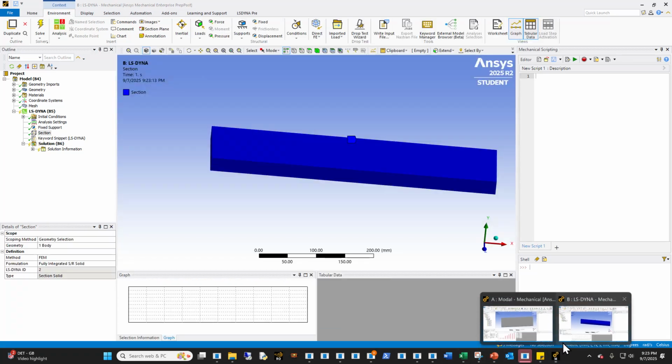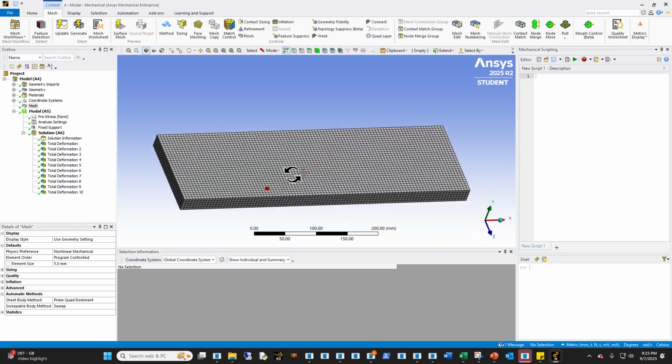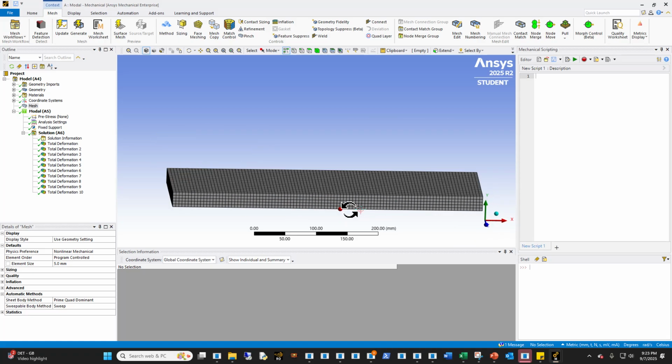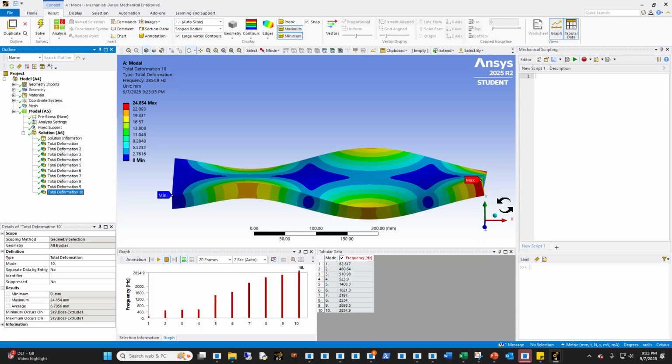In Mechanical, I think you actually default to a quadratic element with compatible modes or something like that, which might be the reason I have a slight difference in my result, right? Now that I think about it, that might be the reason I'm getting zero rotational degree of freedom. But I'll get to that in a bit, okay? But in this case, I have these right here.